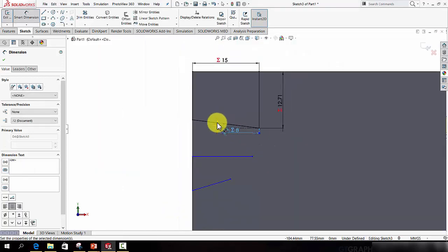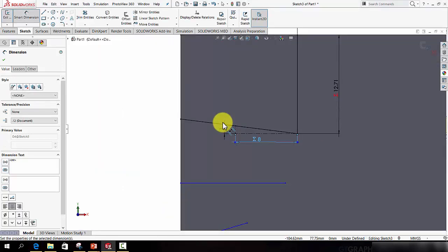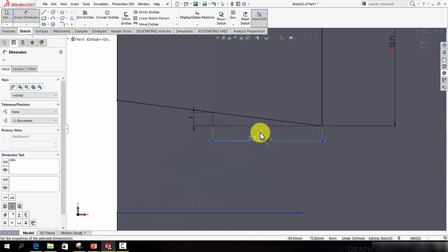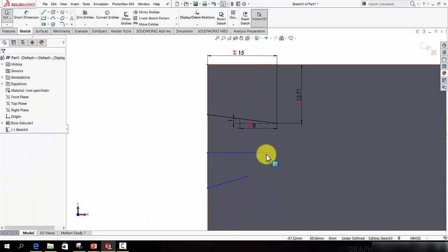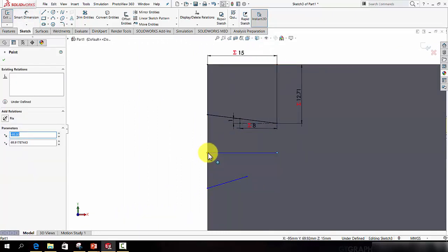So now that's the slope of the dovetail, which is typically either 1 in 6 or 1 in 8, depending on whether you're dovetailing hardwoods or softwoods. But you can easily change the dovetail slope parameter to change this from 1 in 8 to 1 in 6. So let's start drawing on some more of the dovetails. Let's draw the second one on now in a moment.